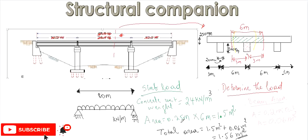So to get the UDL, the total area is 1.56 meter square times 24 kilonewtons per meter cube.